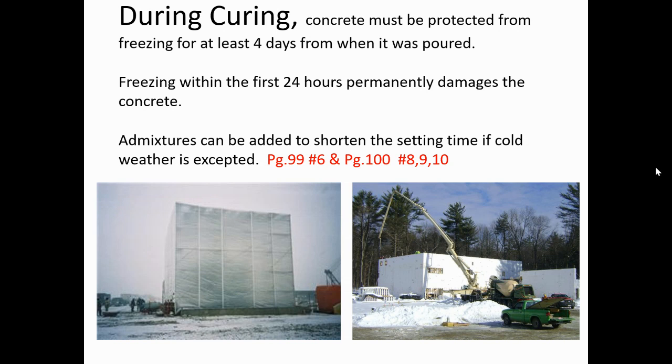Here's a picture of curing concrete in the wintertime. You can see the snow all around. Like I said, you need the water for the chemical reaction. If the water is frozen, it's pretty much like having no water. So you can't let it freeze for the first couple days, and especially the first 24 hours.